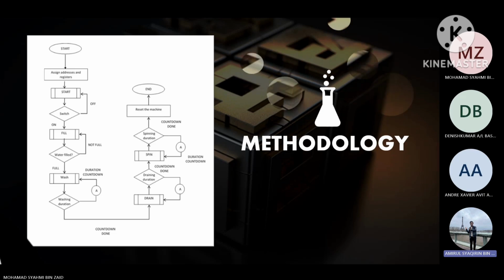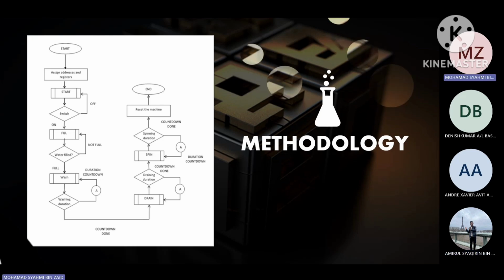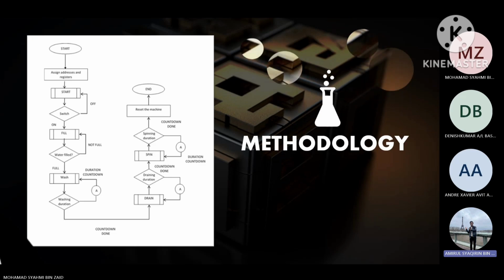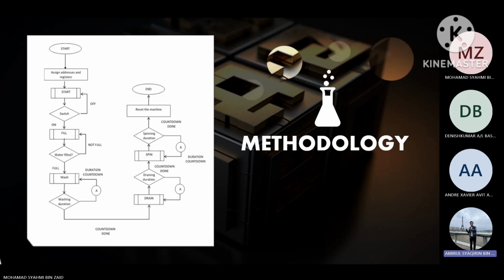Last but not least, the 10th step, after the spin subroutine, it will go to the done subroutine, which is also shown on the 7th segment as done. Then a sound is produced to notify that the process is done. After that, the software goes to the off subroutine to check the state of the switch and clear the display, and goes back to start. Thank you. Next.